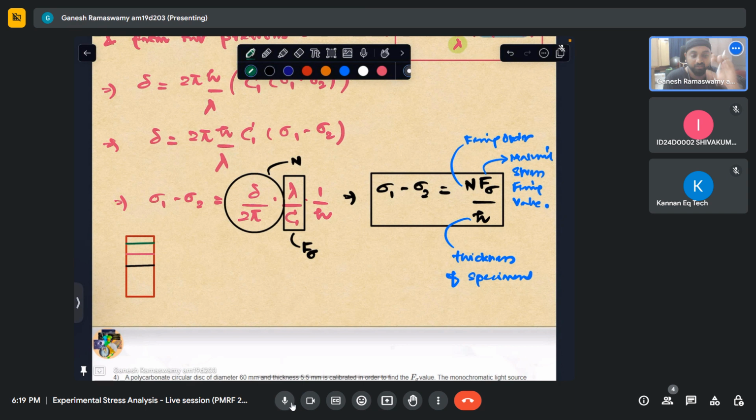Under that light source, we loaded a disk and we generated a calibration table. Not a disk, perhaps a 4-point bent beam because it has straight fringes. So we load that and generate that. So that is specific to that light source. If we have a different light source and we are doing an experiment with it, then we need to generate another color calibration table for that material and that particular light source. So it is dependent on both. I hope that is clear.